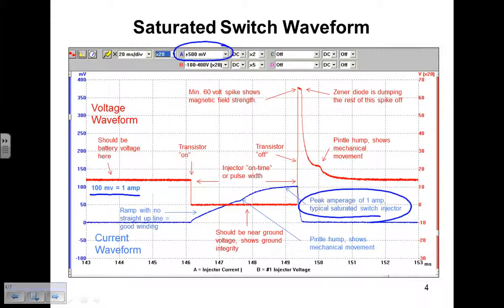That's a saturated switch. When we shot the video on that Chrysler Maserati with injector problems, if you guys remember, we were looking at amperage of around 0.7 of an amp per injector. And we knew that that was okay from doing repetition, knowing at least an idea what they should be drawing. And we said that that was good. So around an amp, just under an amp. So what I'm seeing for the most part really would be about 0.7 to 1.0 amps is probably a better number to go by as far as what it should be when you're looking at a saturated switch fuel injector.